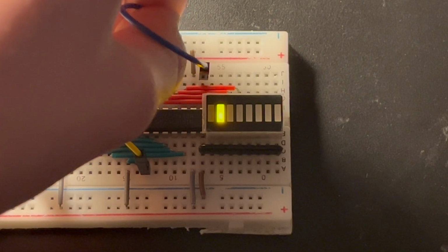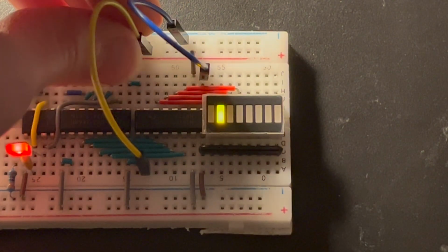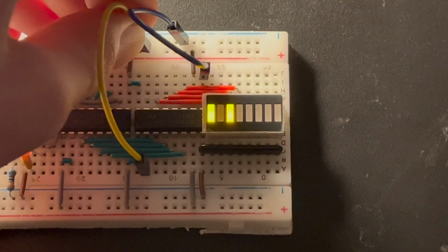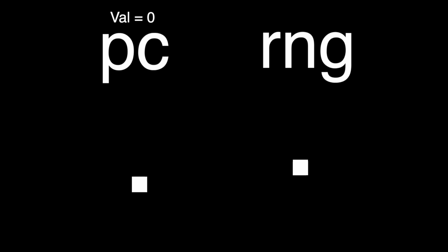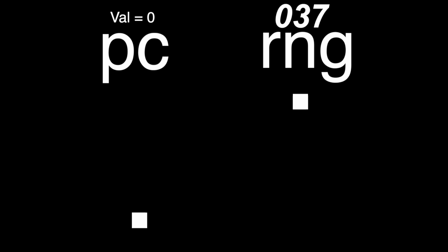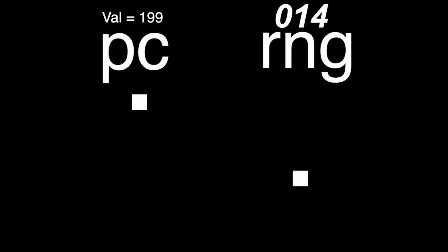Now, let's take a look at the random number generator module, as it is quite simple, but very nice to have in the computer. The core idea for how it works is that the computer's clock ticks at a constant frequency, and so the random number generator has its own separate clock that ticks at a different frequency and counts up all the time. When the CPU wants to get a number, it just takes whatever is in the counter at the moment, but because the module's clock and the CPU's clock are not synced, the CPU can't really predict what number is going to be next, and so it is basically random.